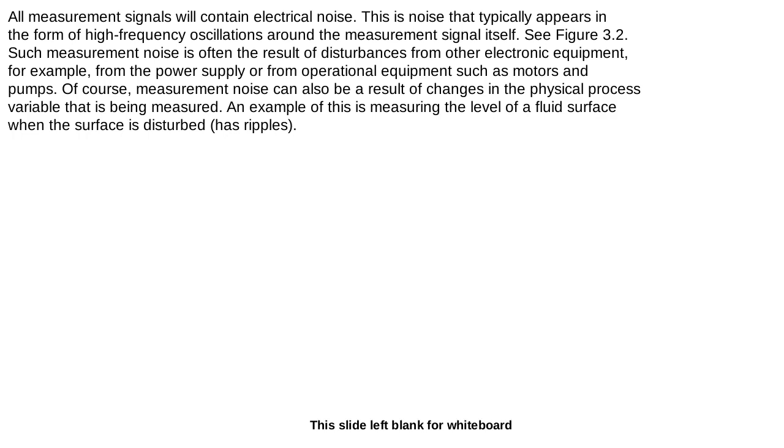So regardless of the cause, it is necessary to filter the signal in order to remove or reduce the noise. And if the measurement noise has a frequency content that corresponds to the natural changes in the measurement signal, then we have a major problem. Then it is not possible for this process of filtering out or removing this noise and reducing the frequency. As mentioned, the energy of the noise is generally in a higher range on the frequency scale than the energy in the signal. And in this way, the noise can be removed or reduced by use of a low pass filter.